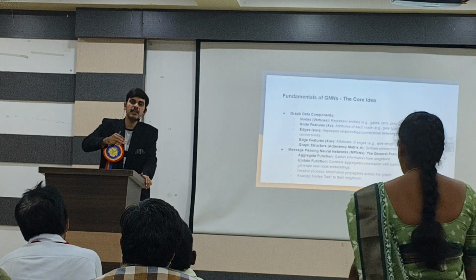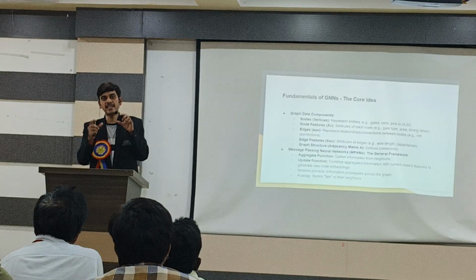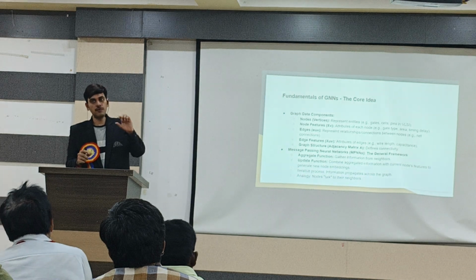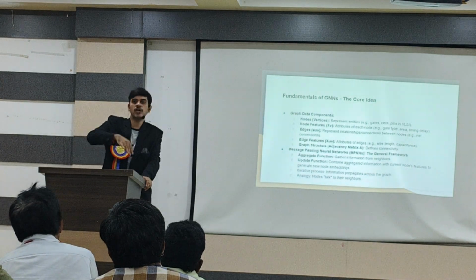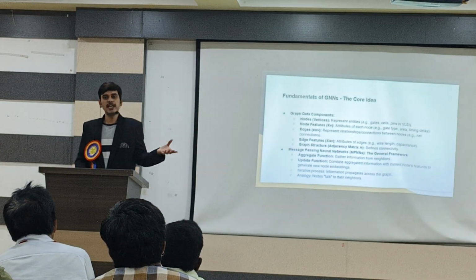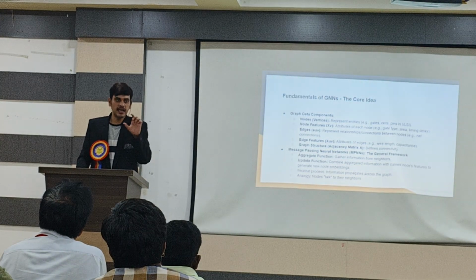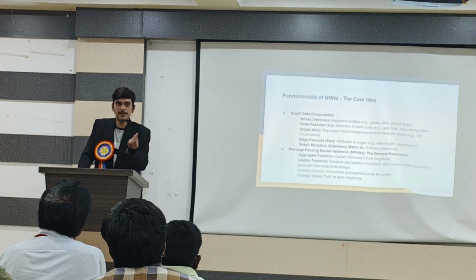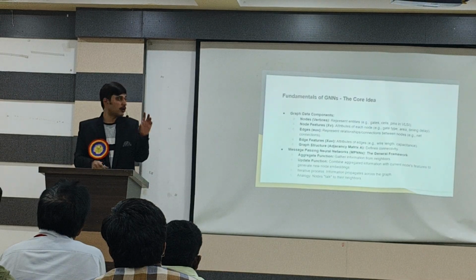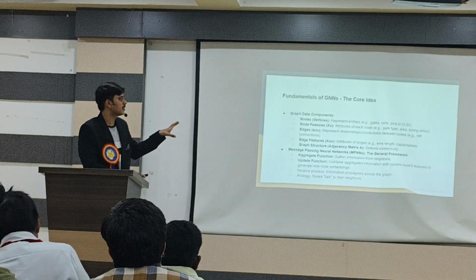For example, if you have a length of 100 micron but you are using D8, it's a waste of area, right? The system should predict that there is no need for D8 inverter or buffer, so it will size it down to D4. Similarly, if 400 inverters need D4 but you use D8, the size will be double. So we have to reduce the size of the chip, because size is a very constrained thing, for example in mobile, where we want to integrate a small chip into a handheld device. So these parameters we should have for writing the GNN data.